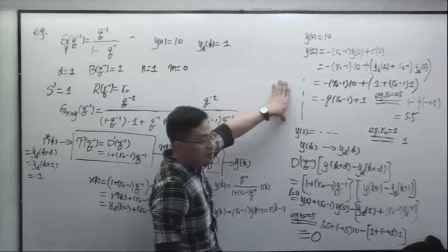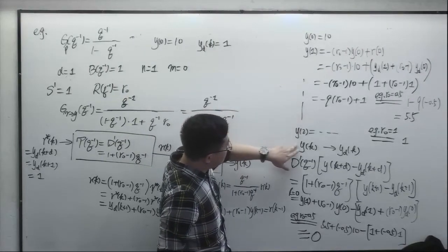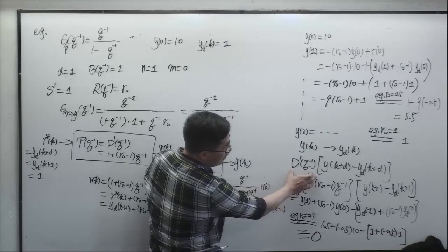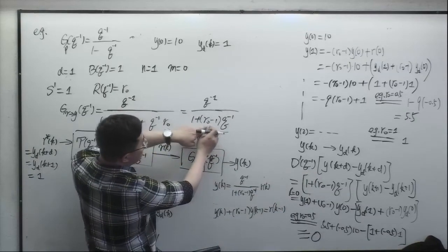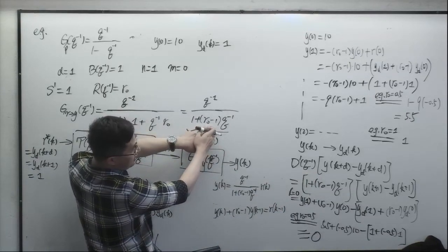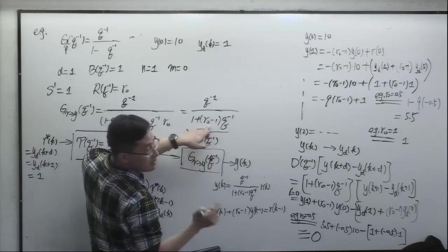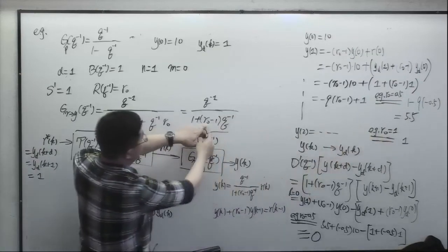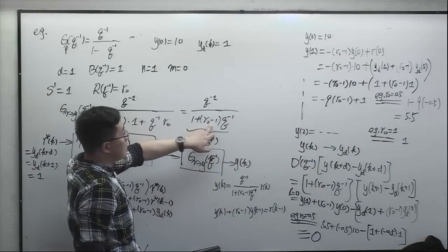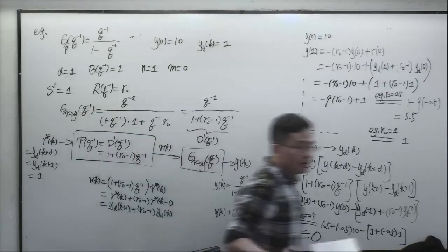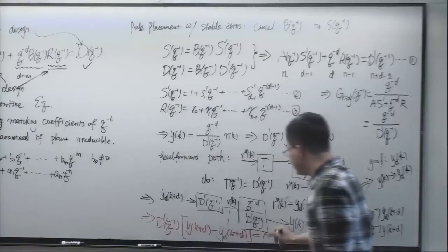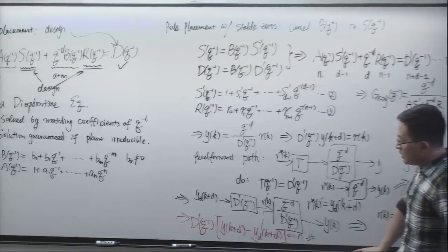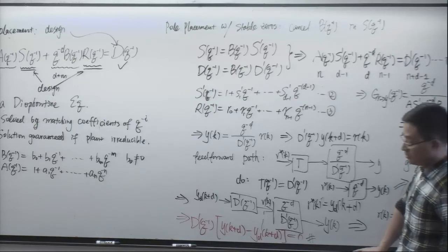So, conclusion. You don't get there directly, there is a transient, and that transient is characterized by this polynomial actually. It's characterized by how you design your closed-loop poles. All right? And the extreme case you can design is to make the closed-loop pole to be at 0 in the discrete time case. So now, we have this important equation. This will become our design goal.